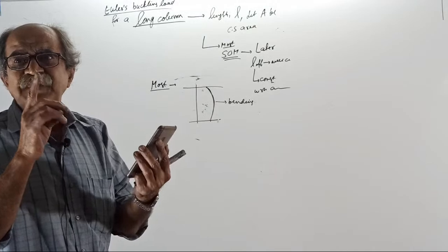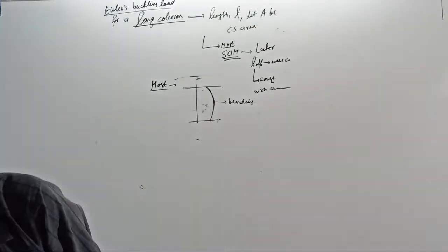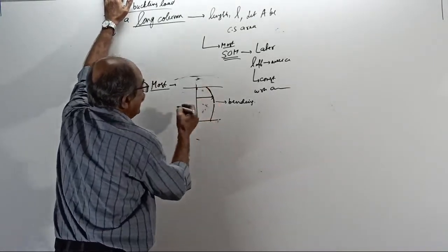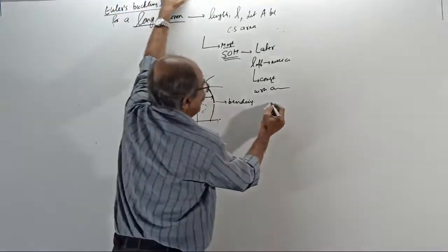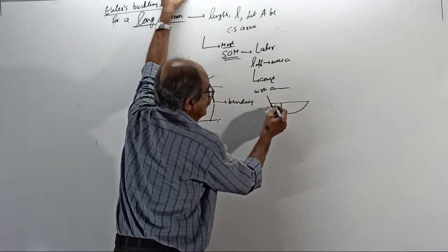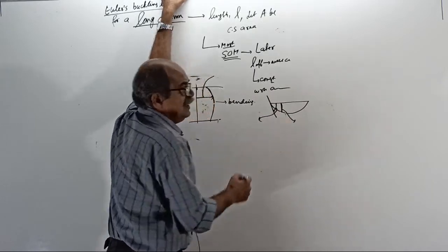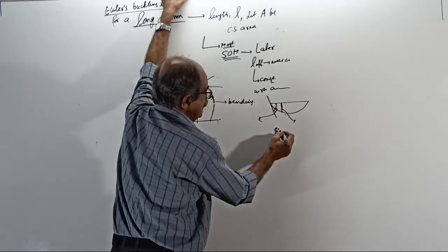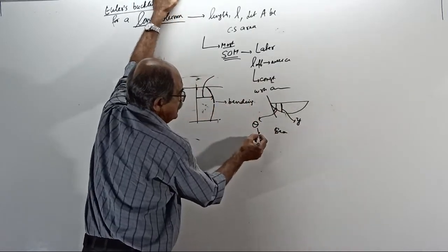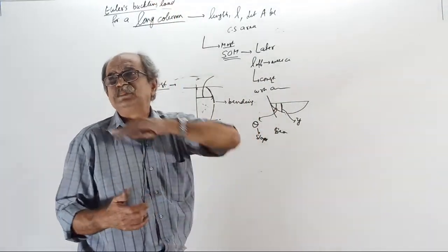See, all these things you should write. If you want to understand, everything you have to write is bending. Yes. Now, from the initial line, what it has undergone here, that is called what? In case of beams, if a beam bends this way, what do you call this one and this one? In beam, this is called theta, this is called y. Theta is called slope, the angle made by the tangent with the beam axis.